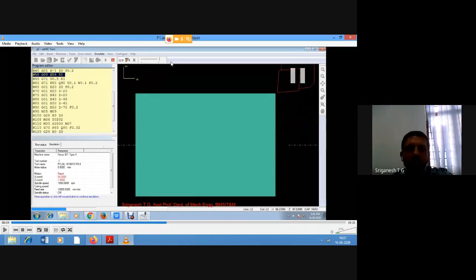Okay, so now next what I'm telling, G00 X56 Z1. So go back there above. Okay, now we have the workpiece material whose 2 mm of material is removed. Okay, that means the length has shortened up by 2 mm, and now onto the right side border it is exactly at 0, 0. Right, that is first thing. Second thing, any measurement of the coordinates that we are giving over here is going to start measuring from 0, 0. Right, so both are matching. Okay, so we don't need to make some adjustments for the exact dimensions to appear. Okay, right.